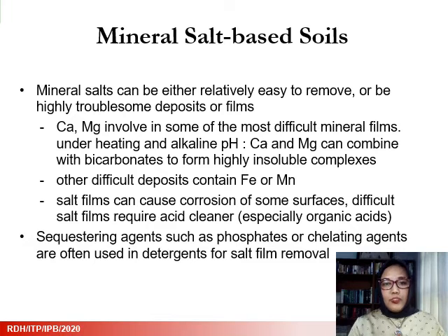Mineral salt-based soils can be either easy to remove or troublesome deposits or films. Calcium and magnesium are involved in some of the most difficult mineral films. Under heating and alkaline pH, these minerals can combine with bicarbonates to form highly insoluble complexes.